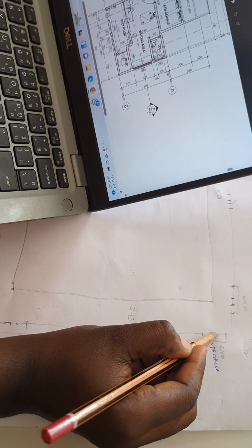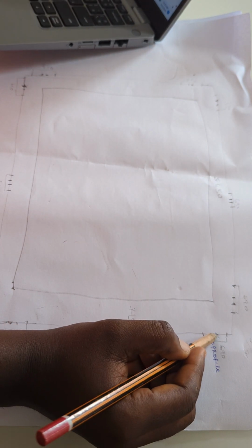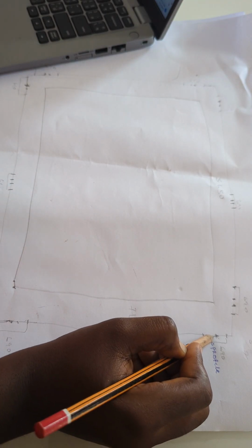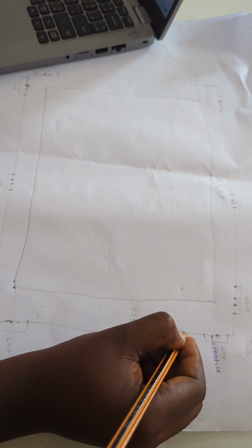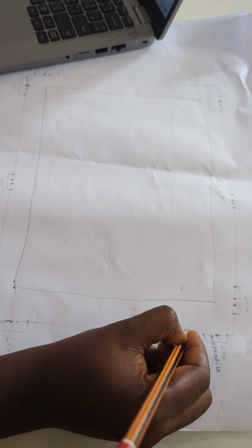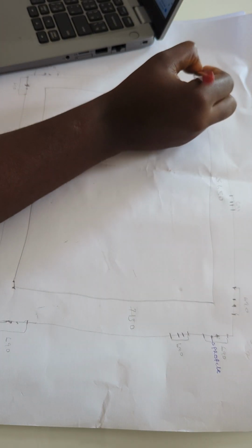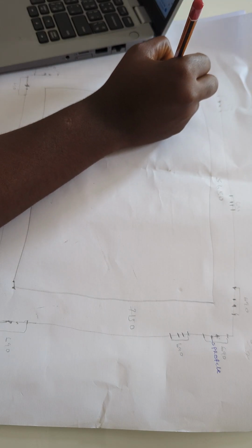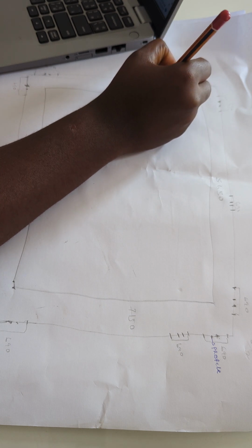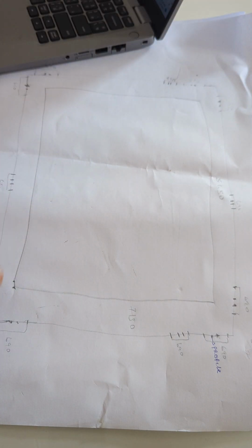The first in to in means from this point we have 850. All right, so this is the point, this is the in, because you come in by 150. So we are looking for 870. Assuming our 870 ends here, you are going to come out by 150. You are going to do your excavation of 270. You are going to do your excavation of 270. So the whole of here will be 690. Do the same thing for this side. Come in by 850. I'm trying to ensure that at least we have 850. Come in by 150. Come here by 270. Go back by 270, and then you have your 690. All right, is that clear?